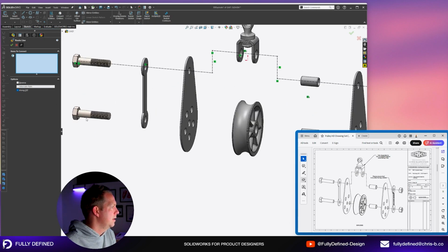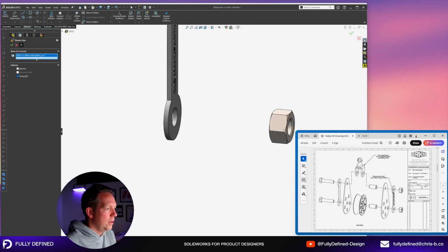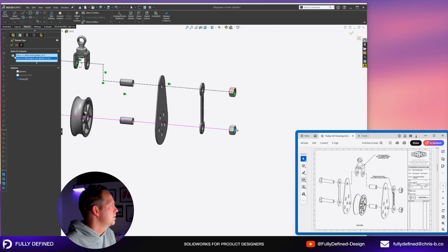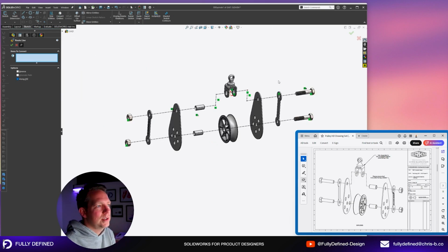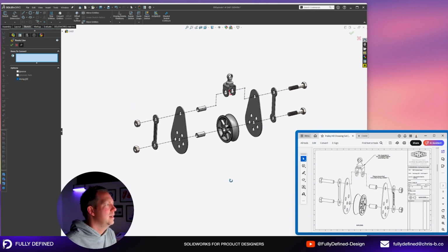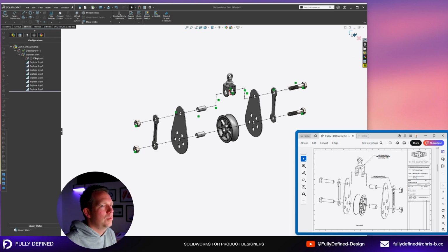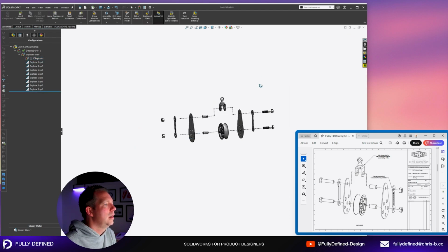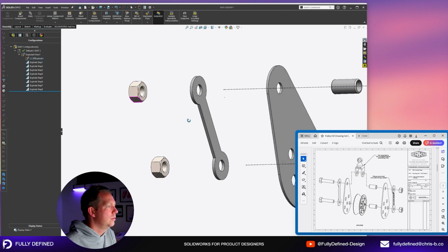I'm going to do the same thing down the bottom, but this time I'm just going straight all the way through. So I'm just clicking the first and the last points and press OK. Now if I want to exit this tool, I press the tick. Hitting the cross may cancel everything that I've just done, so I'm not going to do that. But if you've already done your route lines, you've been editing them, you made changes, and you want to discard changes, then you can hit the cross. And then press accept to leave the 3D sketch. And now those are part of the drawing.